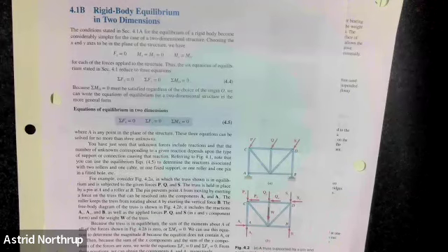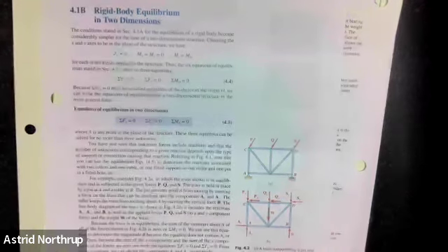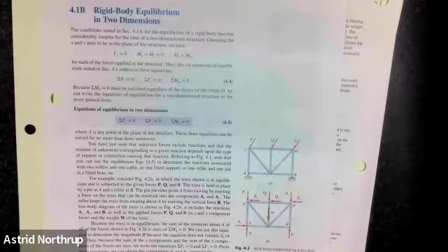Now, the reason for that practically is, if you think about how a bridge works, a bridge will tend to be spanned upward, first of all. You know, when it's not loaded, it'll be like an arch. Then it pushes down. What happens to its horizontal length when that happens? Yeah, it expands. And so if you anchor up both sides, if you have a fixed support on both sides, it's not going to be able to move in response to that load. Also, cold and hot expansion, and just other things that happen with materials.